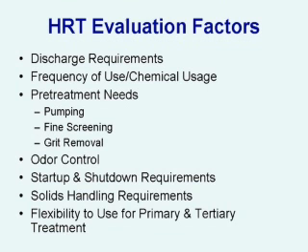Flows then enter high rate clarification, which is in the center top of the screen. As flows pass through high rate clarification, they are initially sent to the equalization basin until such time as the equalization basin is full. And then those flows leave the plant through a chlorine contact facility and reaeration. Some of the flow from the high rate clarification actually enters the secondary process, the aeration basin, because there is more capacity in the secondary treatment than in the primary treatment at this plant.